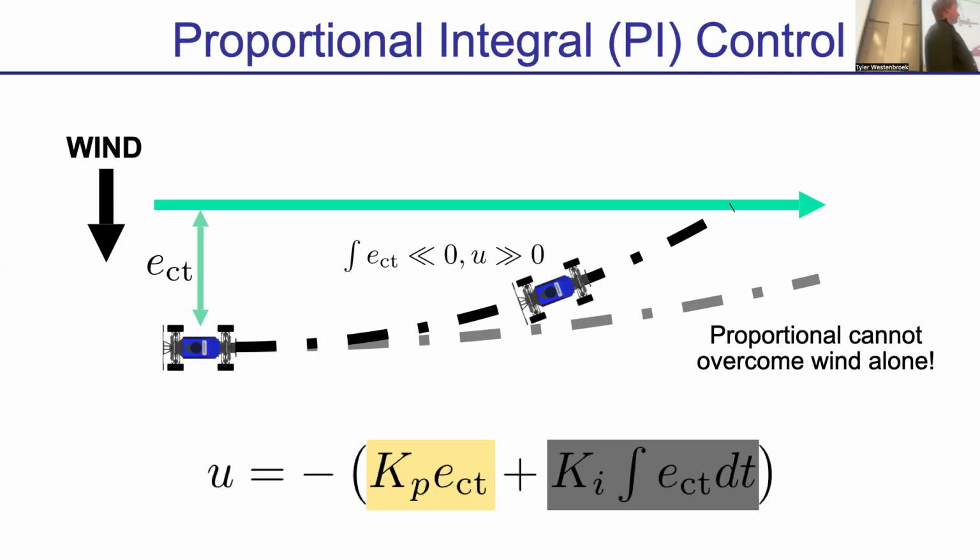Right. And so if I have these steady state tracking errors, what it's going to do is look at those and say, okay, I'm not pushing hard enough to bring myself to where I want to go. And so the longer that I'm not there, I'm just going to keep pushing harder. I'm going to wind up the control effort accordingly to slowly push my system to where I want to go.